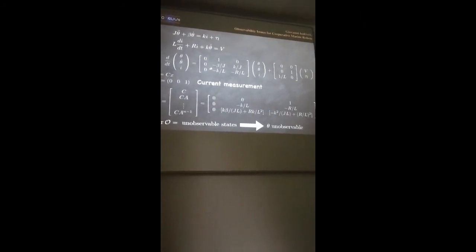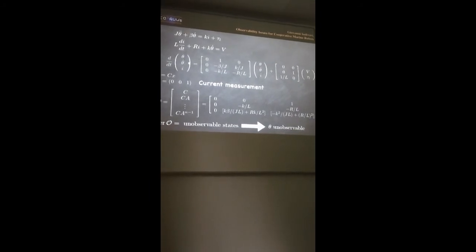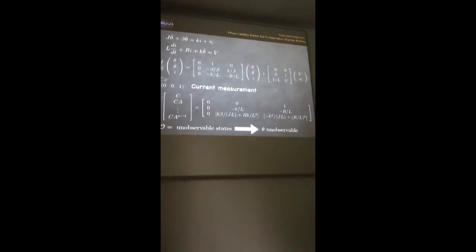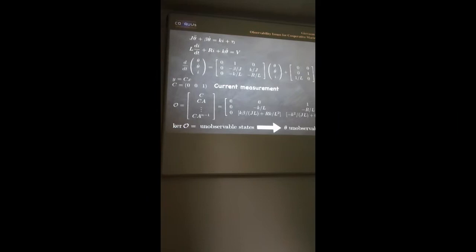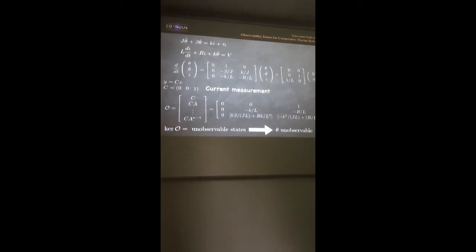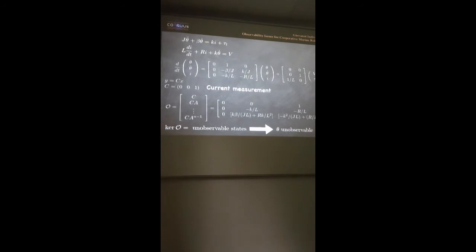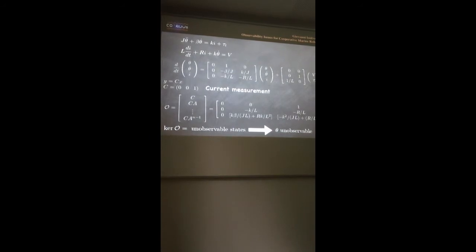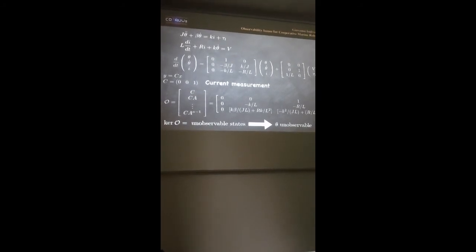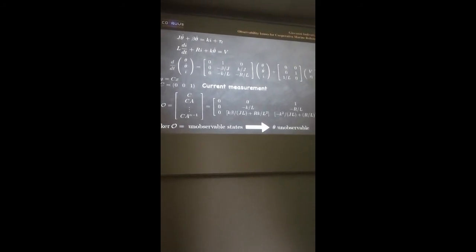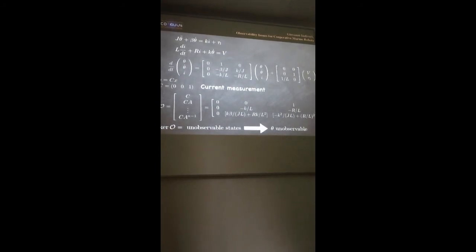And if you measure directly the angular velocity of the shaft, this is also very useful because, although we didn't go into the details yesterday, I'm telling you now, the basic hydrodynamics is telling us that the thrust that you produce by a propeller is proportional to the square of the angular velocity. So if you can measure the angular velocity of the propeller, or even better, if you can actively control in feedback the angular velocity of the propeller, you have a good way of calibrating the thrust that you are producing. Okay?